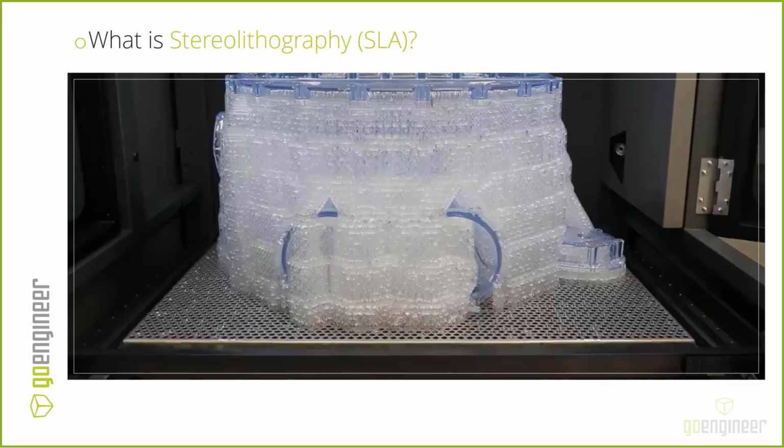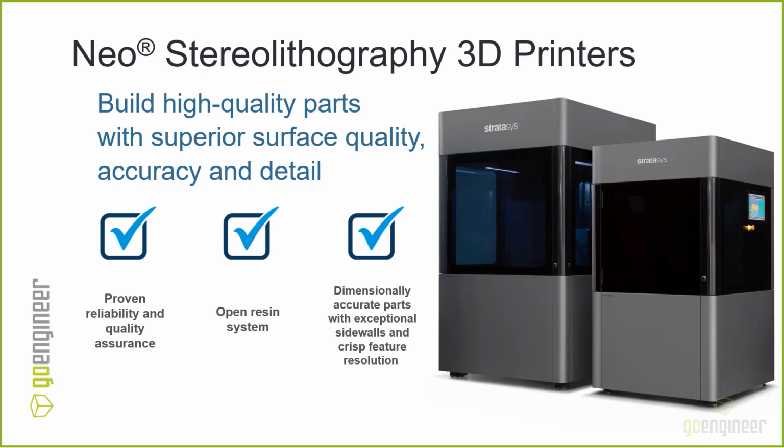So the key takeaways for stereolithography, especially the Neo line of industrial grade 3D printers, are that they can produce accurate parts with superior surface quality and exceptional detail. They're high repeatability, high volume, large parts. And so if you have a really big part that also has very fine features, this is an excellent technology to use. The primary use cases are single material concept modeling, prototyping, and investment casting applications. And then a secondary application would be rapid tooling.